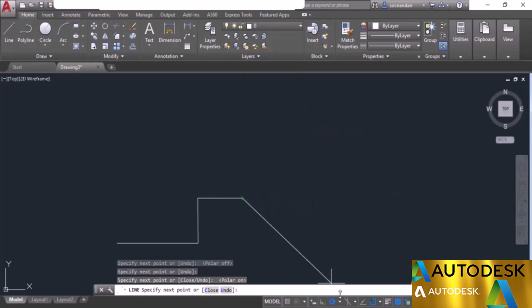For that, click on this small arrow right beside this polar tracking and change it to 30. And here we have this 60, 90, 120, 150 and so on. So let's click here. And now we have the first angle at 0, then the second tracking vector at 30, then at 60, 90, and so on. So after every 30 degrees, we have this tracking vector, and that will make the drawing workflow very easy, and you will be able to directly snap to those angles easily using this polar tracking tool.